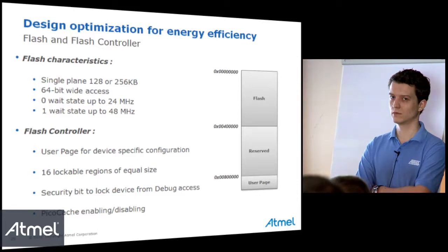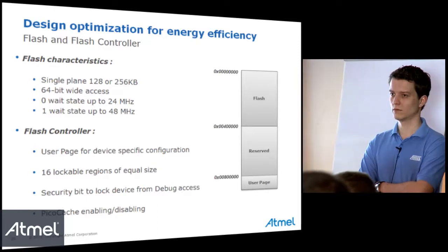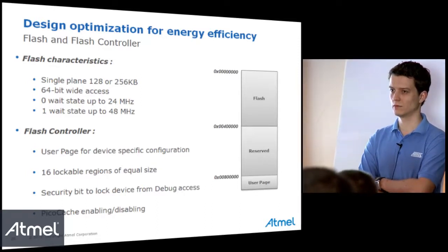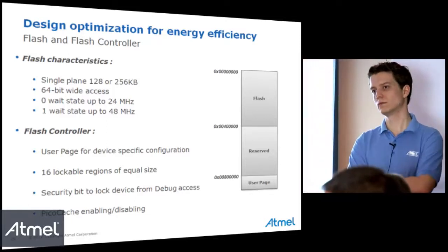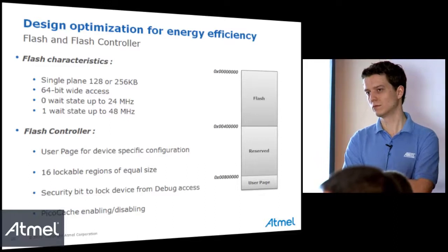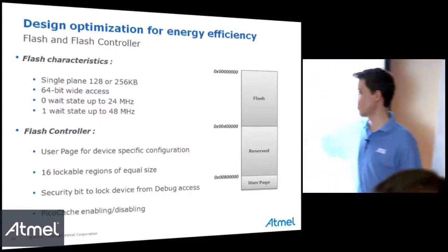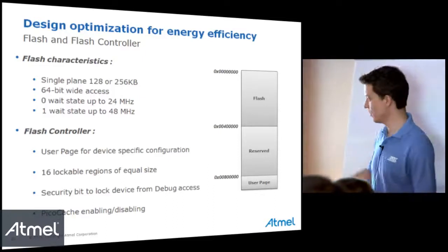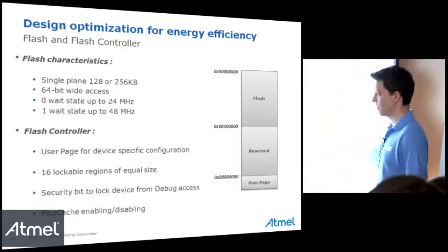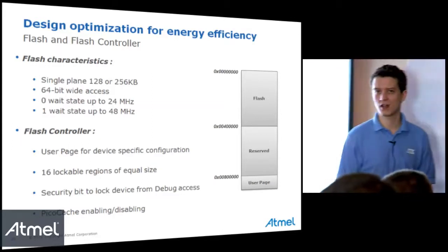Okay. And just in case I want to guarantee my customer that he can lock his software and nobody can reuse it for making or running a fake application, can a lock bit for the flash be used? You mean the lock bit? The lock bit is only for writing, not reading. The only bit that secures the chip is this one, but you will not have JTAG or SWD access.